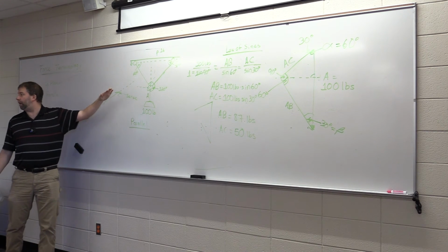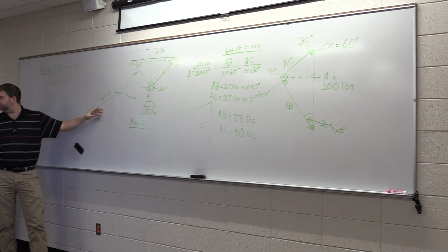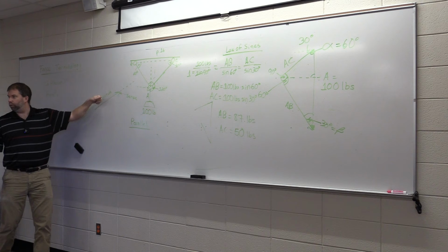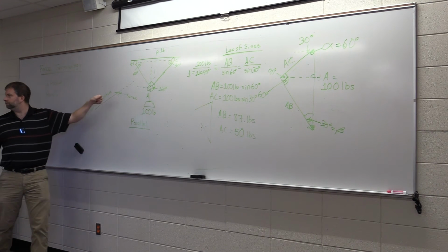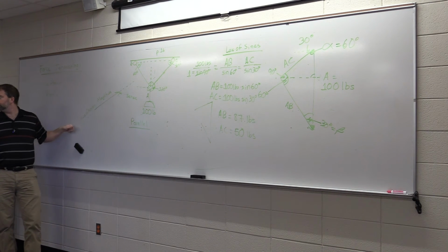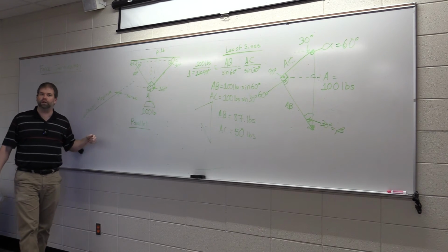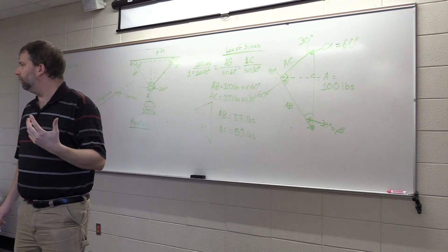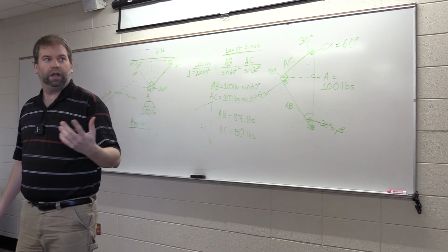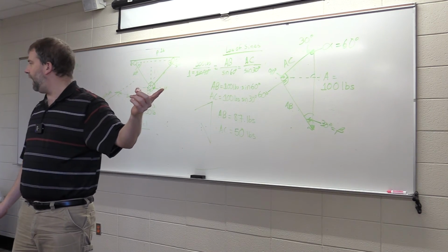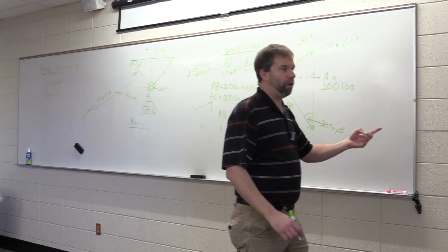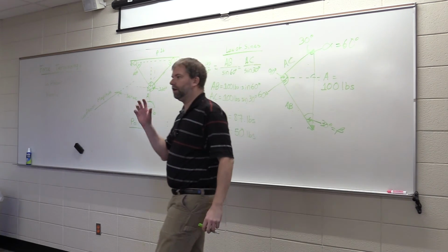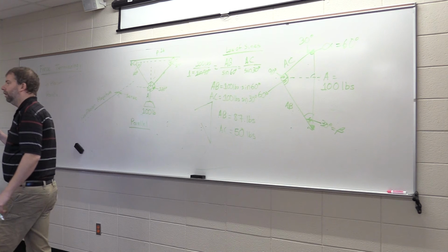Now, a thing to remember about a force is we can move it as long as we don't change its sense, and as long as we don't change its magnitude, we can move it anywhere along its line of action, okay? Think about if we were to throw a baseball with a force of 50 pounds at this wall. Does the wall care if we throw it from here with 50 pounds, or from here, or from here?